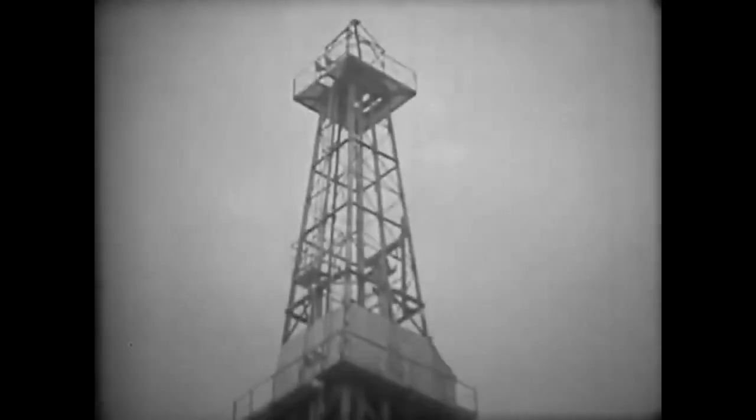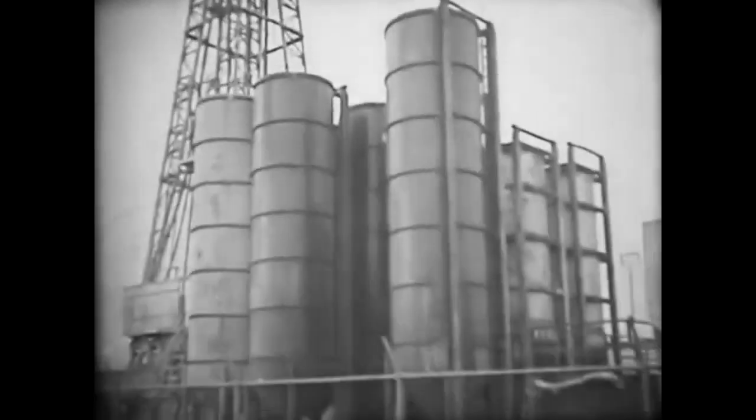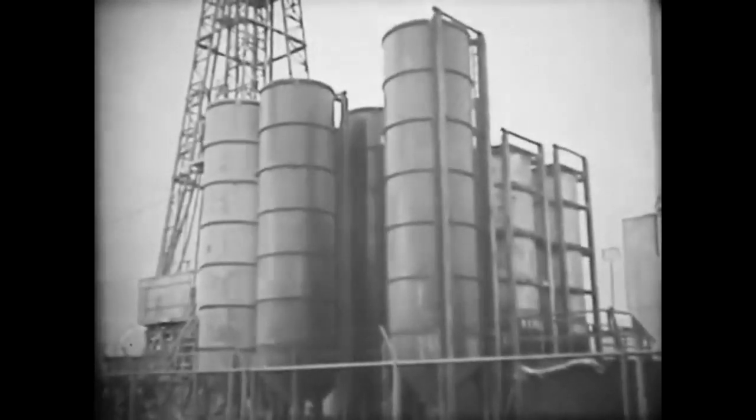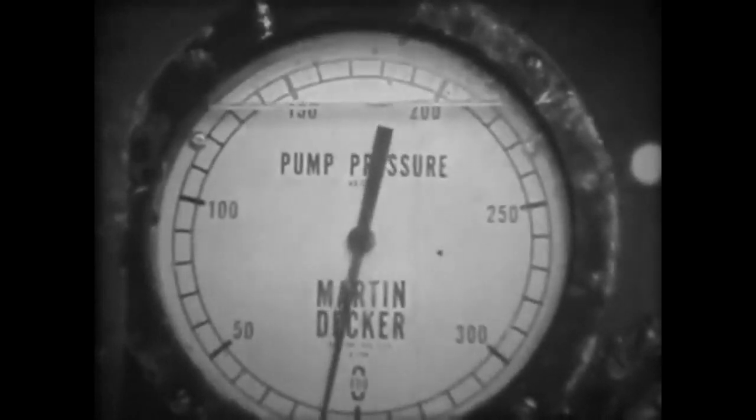It's flowing into the well and forcing out the mud. Before we can drill on, we have to contain the formation pressure by pumping down a heavier mud. This is usually kept in the storage tanks ready for just such an emergency. At 3,500 feet below, the gas is flowing into the hole. But as the new heavier mud begins to circulate, the pressure is gradually overcome, and the flow stops. As the pressure returns to normal, the emergency is over.